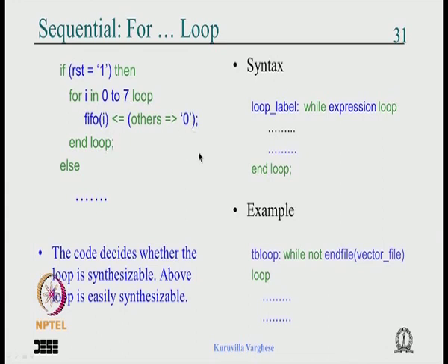So it is not a great problem, it is very easy to synthesize, and people make a very generic statement like "loop is not synthesizable", which is not true. As I said, it essentially means that you have an algorithm where a loop is there.